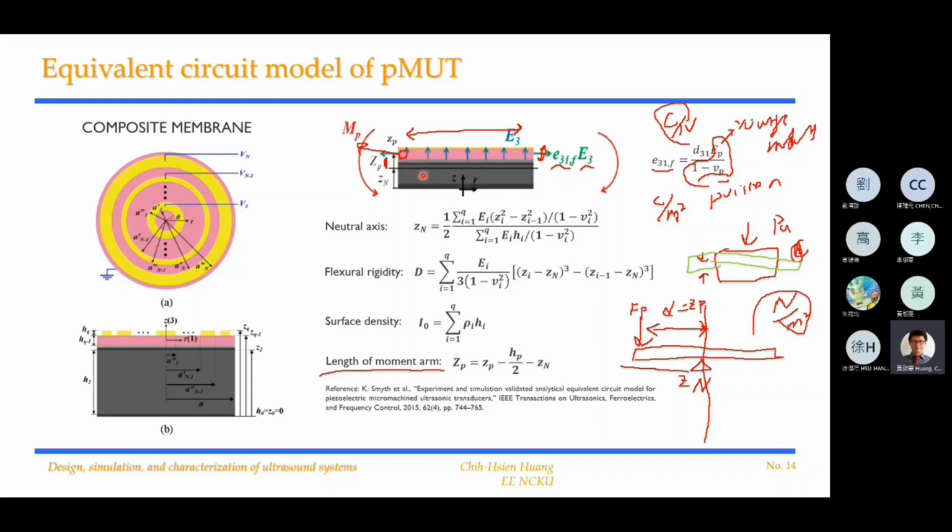But if it's too thin, then your neutral axis, let's see, if this layer here is very small and your piezoelectric is relatively thicker, then the neutral axis may move into the piezoelectric layer.